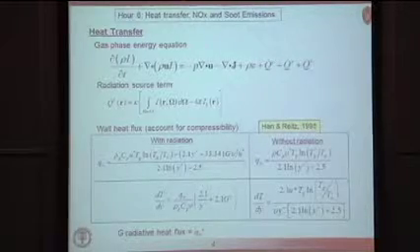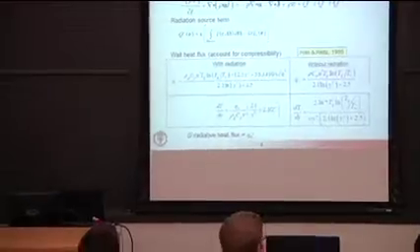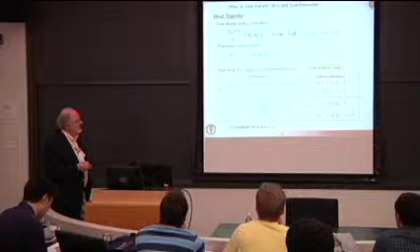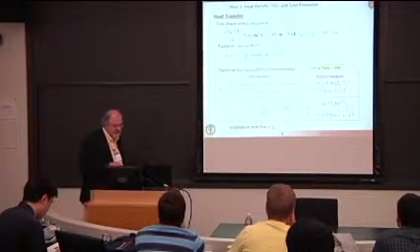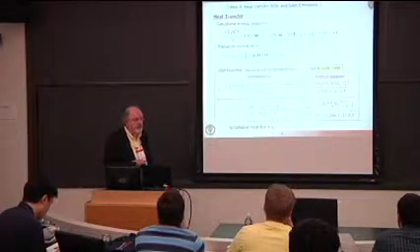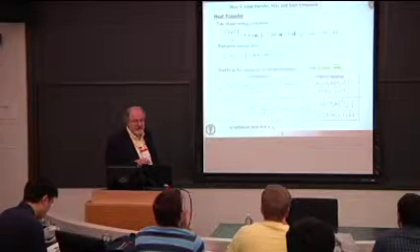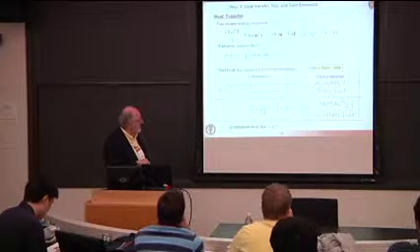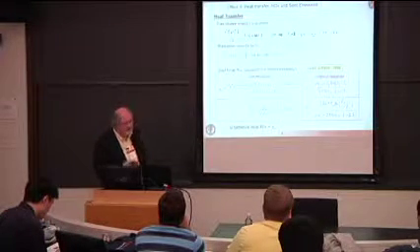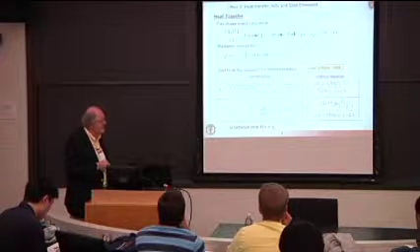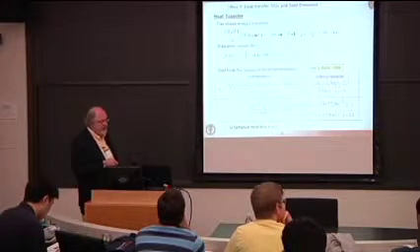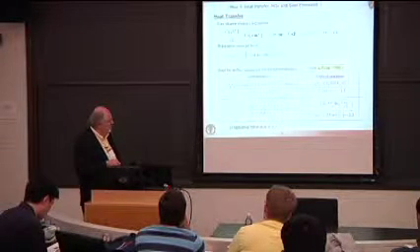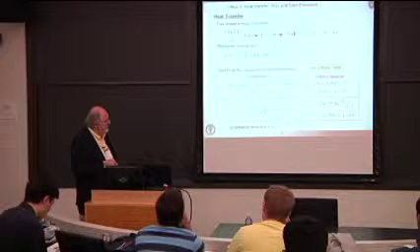But before we get to discussing that, we also need to worry about how we treat the wall heat flux. I mentioned to you before that we had improved the log law of the wall to account for compressibility effects in an engine. And so back here, Alan Hine and I proposed a wall heat transfer or heat flux expression that essentially is a modification of the log law of the wall that accounts for the fact that the density is varying due to compressibility effects.